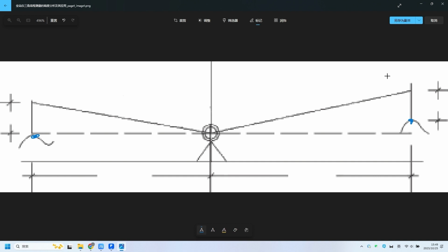We only need to observe the height difference between the center point of our instrument and the two target points, and the accumulated height difference is actually the height difference between these 2 points. In this measurement process, the location where the instrument is installed is only temporary. This point is only used once, just like when we push the leveling line, it is randomly set up and left after use. Therefore, this place is an arbitrary point.